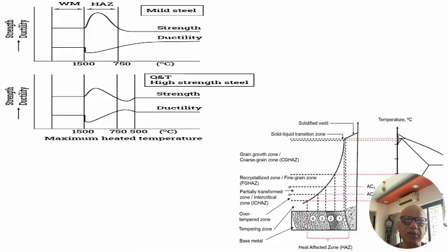It also depends on the material properties. Some materials have a high coefficient of expansion, so they will expand and contract to a larger extent. There are some materials which have very low coefficient of expansion. Similarly, thermal conductivity: a good thermal conductivity like aluminum or copper will flow the heat and make the entire surface hot. Materials like stainless steel, which have poor conductivity, will accumulate the heat. Mild steel, which is good in all aspects of these physical parameters, is always good to weld.